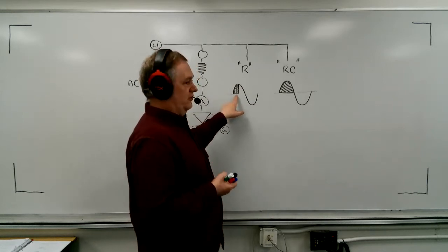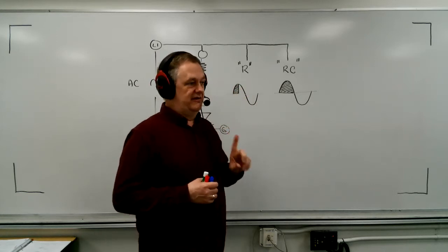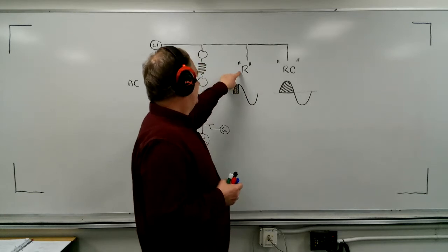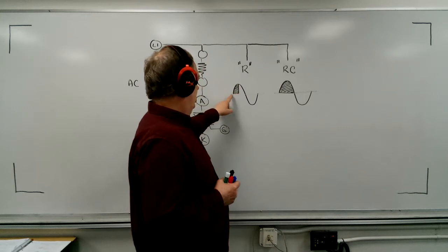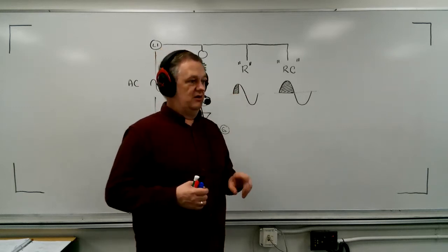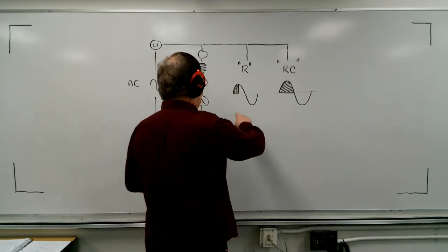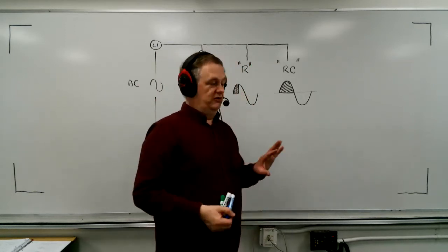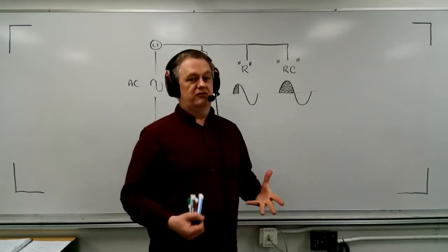In a resistance only circuit, if you look at one cycle of AC voltage, this is what it is capable of controlling, and it's only from 0 to 90 degrees. If you don't fire within that time period, what you're going to see is just an AC waveform. There'll be no load current whatsoever. You'll see across the SCR a whole AC waveform. It's like an open switch.